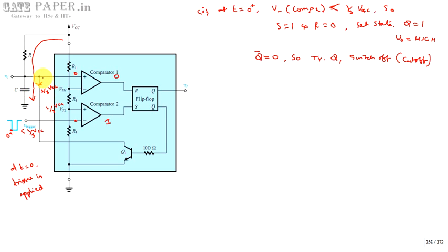The current doesn't flow towards this capacitor. Okay, now as this connection is not present, since Q1 is cut off, which is nothing but open circuit, no current flows. So definitely now the current coming from the VCC will go through this capacitor. Now capacitor starts charging. Capacitor charges always exponentially.